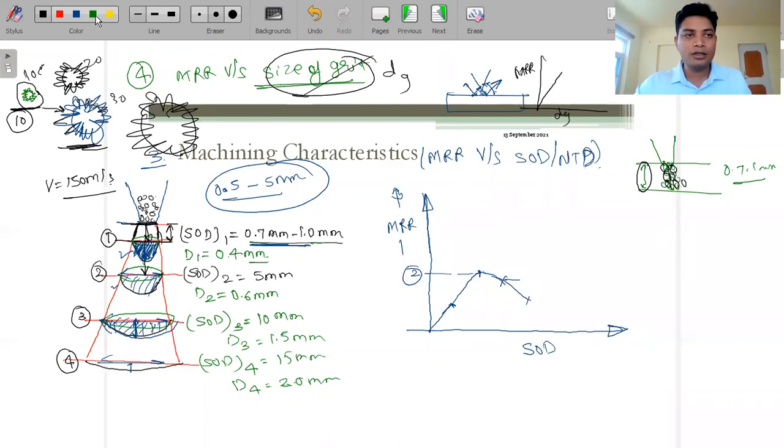So you have to see this area as well at this time. By the way, the abrasive particle has been released from the nozzle, but the distance has been completely covered by this abrasive particle. You getting my point? This space between the nozzle tip and the workpiece surface is completely covered by this abrasive particle. So where will it impinge? There is no space for impingement. As it is coming out, it is directly jumping over the workpiece surface.